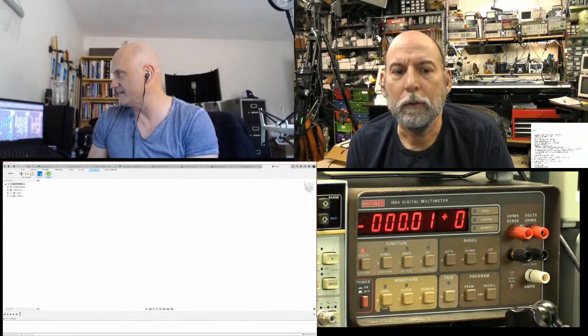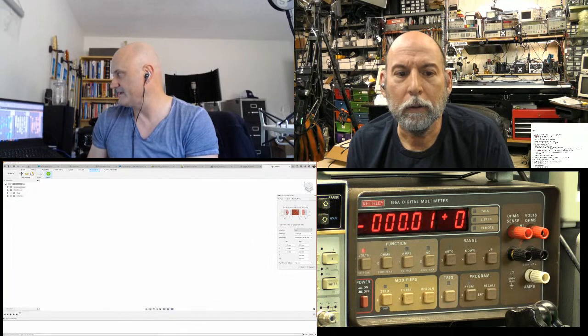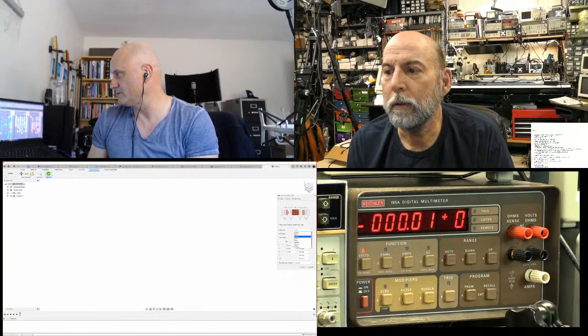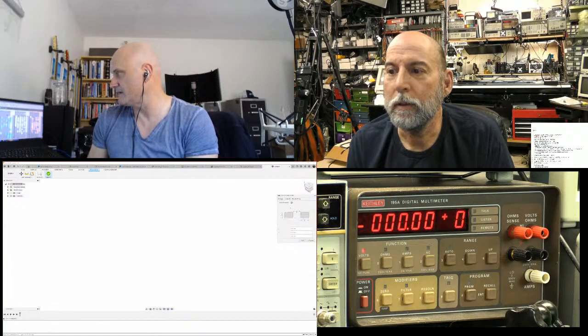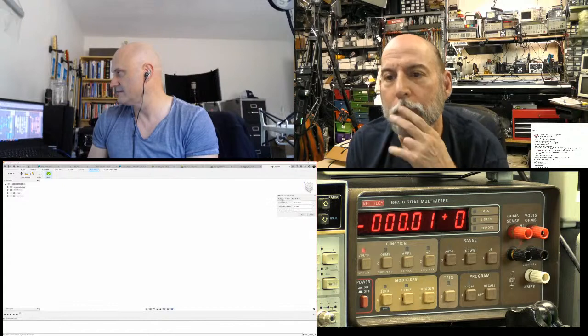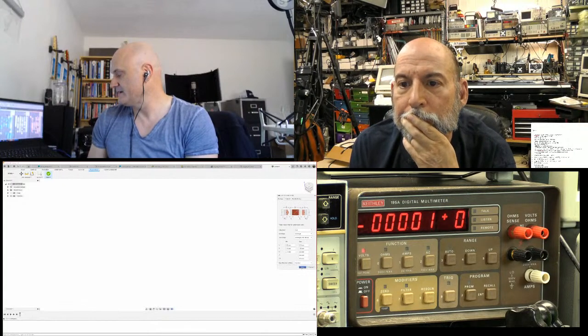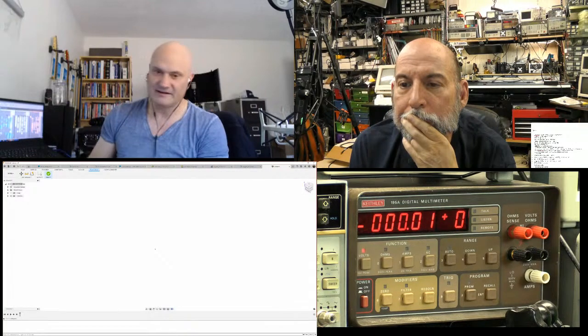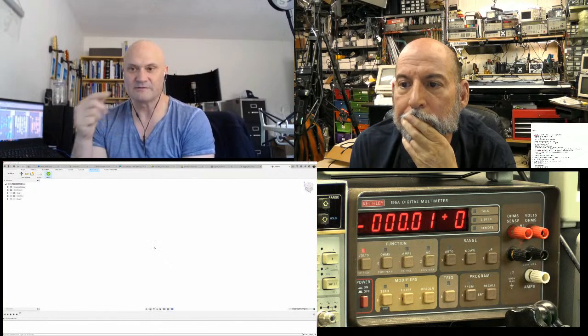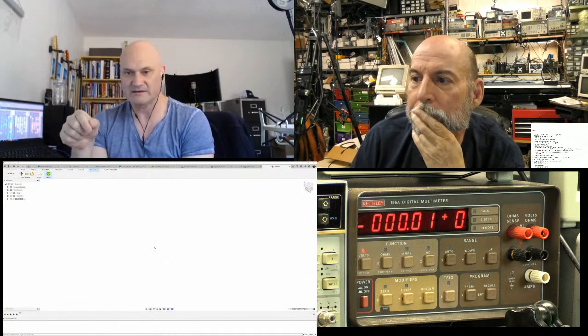And so I can make an LED, and I can specify the color I want. So if I want, let's do a blue LED. I think the default size here is an 0603 package, and I can override the footprint pads and look at IPC least, nominal, max, and click add. It doesn't just generate a footprint here, it also generates the 3D model to go with it.